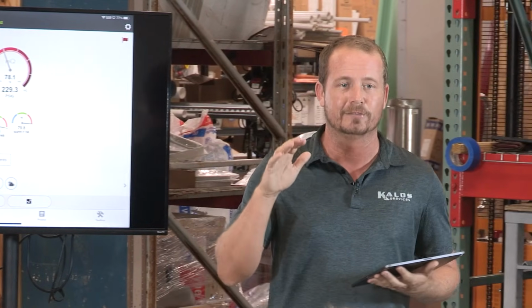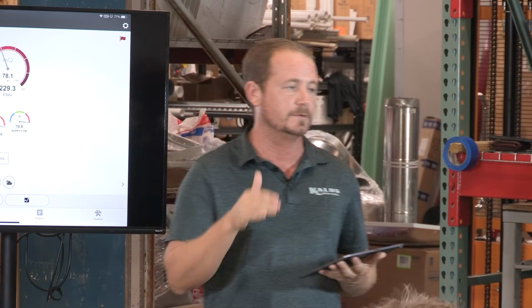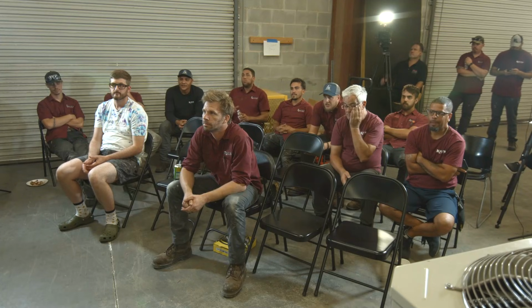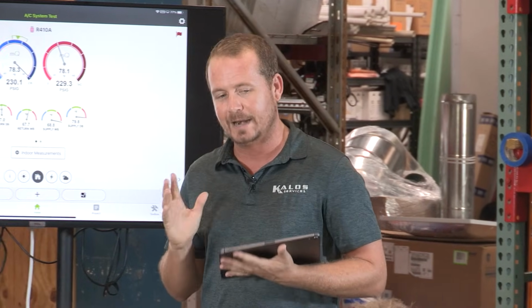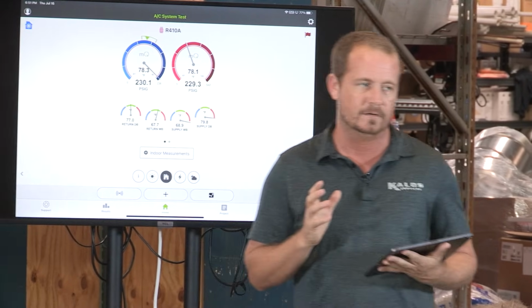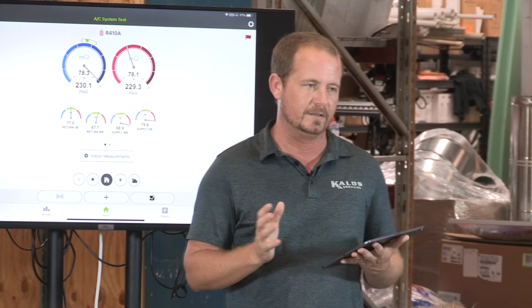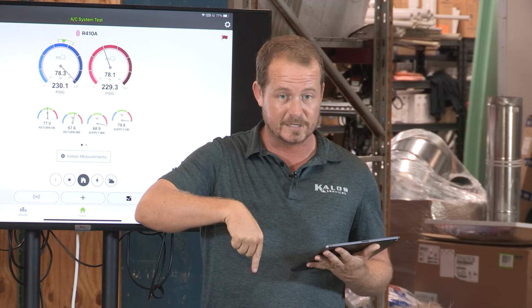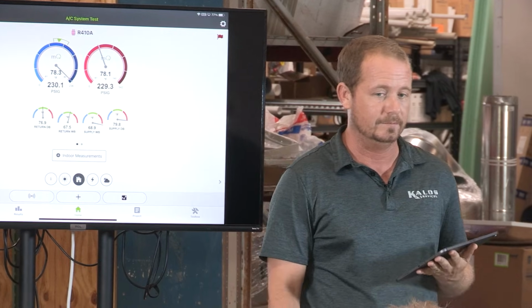But now let's say that you have low airflow. And so when you have low airflow, you're going to have a lower evaporator temperature. So now let's say our evaporator temperature is 35 and we have 10 degrees of superheat. Now what's our suction line temperature going to be? 45. Got it. This is kind of a neat thing. Now we're talking residential air conditioning here, but if you measure a suction line temperature that's below 50 and the temperature inside the space is normal, very good likelihood you have low airflow, right?